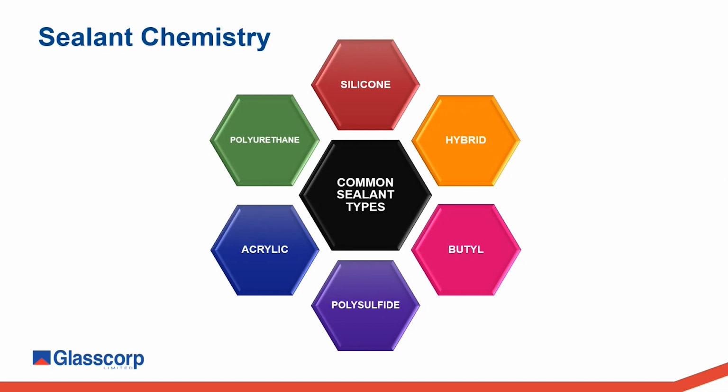And like many other organic sealants, they have the advantage of being paintable. On the other hand, they tend to have limited movement capability, and so they're not used in high movement applications. In the next few slides, I'm going to be going a bit deeper into the other three sealant chemistries listed here. So that's silicones, polyurethanes, and hybrid technologies.